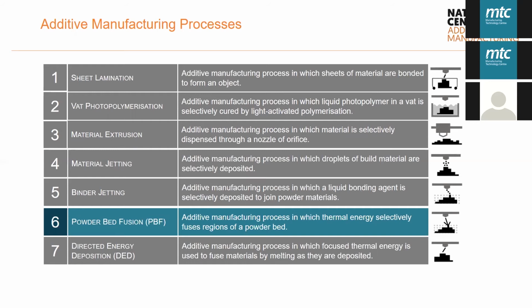It's very reactive, so it's quite difficult to manufacture using indirect additive AM processes, mainly because there isn't a reduced environment in the processing itself, or sometimes the debinding. It's not saying that it's not being done. There are systems out there that offer Ti64 as a material that you can process with. So I think Digital Metal, I believe Desktop X1, most of them do offer it, but it is quite difficult potentially.